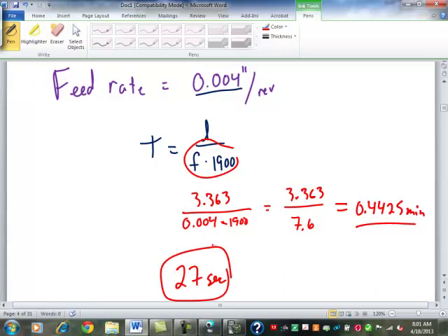That's actually, the 4 thousandths is a pretty healthy feed rate going through steel. To make a 3-inch bore, you'd take at least a minute. I would say about 2 thousandths is more of your feed rate on a drill, a 1/2-inch drill. Any questions?